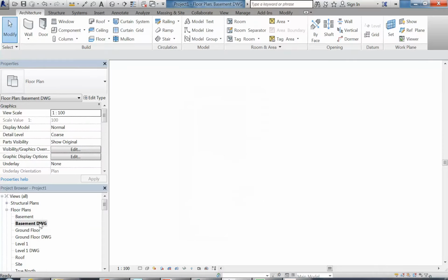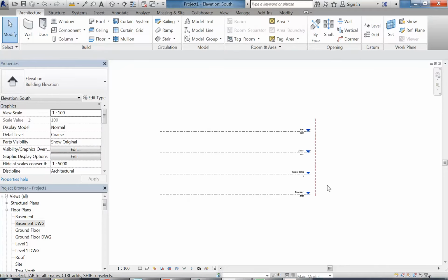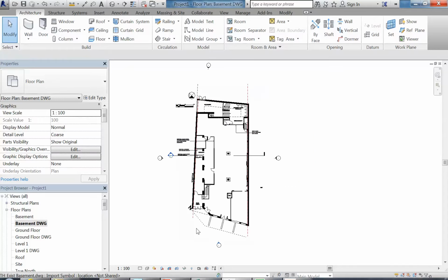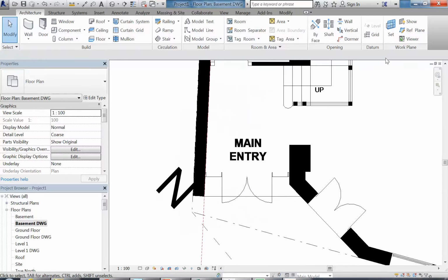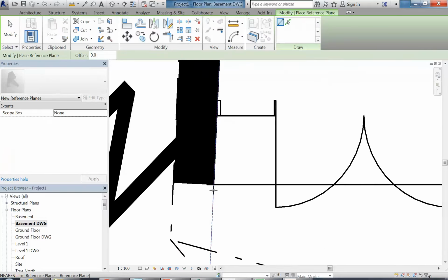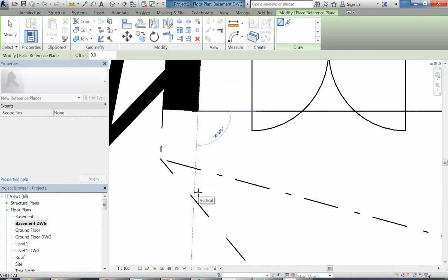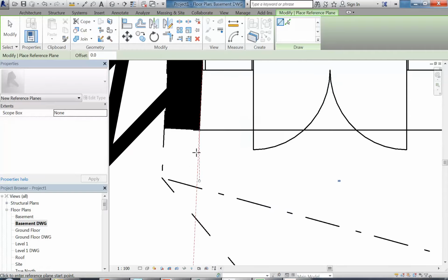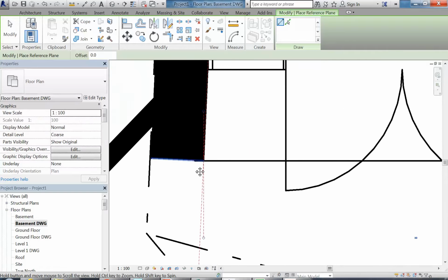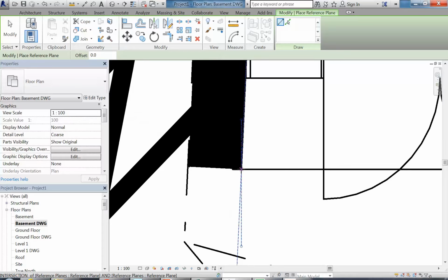And it can be helpful to be able to see the width of your building or your space in an elevation view from the beginning. So there's a little trick there I can show you. If you just draw a reference plane from one of the corner points and make that perpendicular, so at 90 degrees, in other words. And that will be a useful thing in many situations. So here I'm going to draw another one that is at 0 degrees, coming out from that corner.